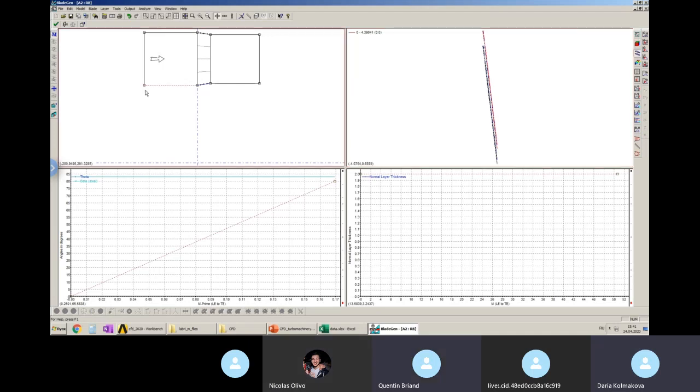So you need to double click on the point to correct its coordinates. For the left point, the horizontal coordinate will be -50, and for your projects as well, the coordinates will be the same. We know that this coordinate is 50, and half of the axial gap is 5, so the horizontal coordinate for the right line will be 55.